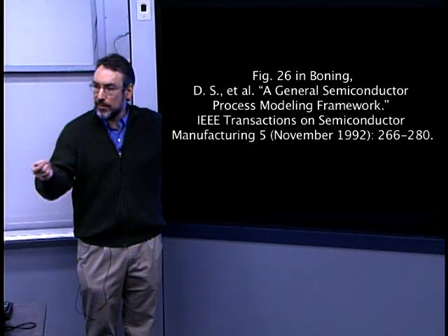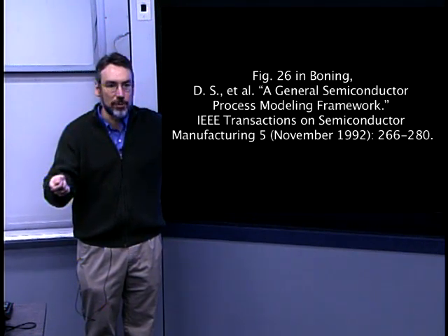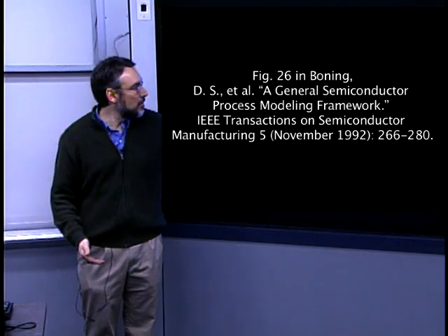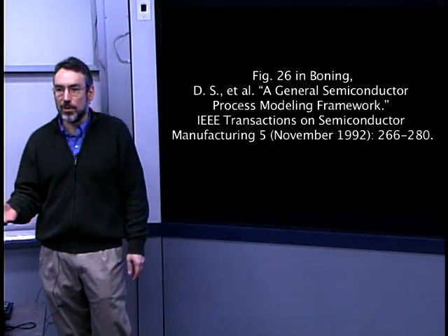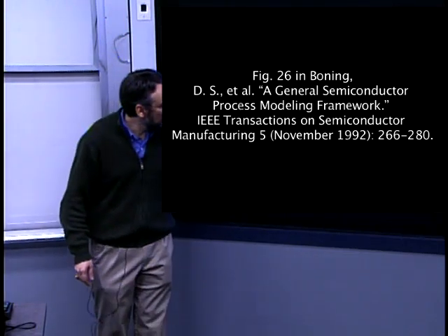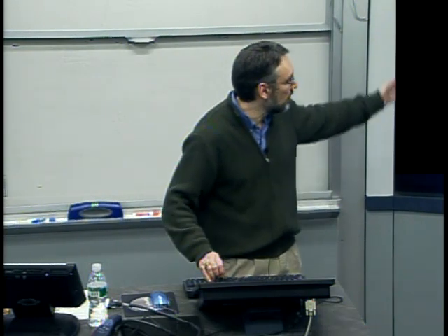In this case, if there's variability in the starting wafer, or the wafer as processed up to some step, that might interact with the step that we're now performing and limit our ability to control. And then similarly, there may be influences of variation coming from the machine or the facility or the wafer environment. So what I want to do is talk a little bit about some of those different kinds of variations and build on what we've seen here.